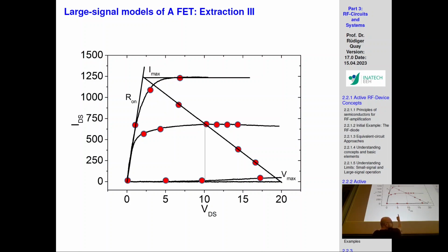how much is the swing of your input voltage, whether it's a complete period, or whether the one side is only positive and the other side is cut off, and what the effects are with respect to the output. Probably this was given in other lectures, so I don't have to introduce that now, but more operating points are selected, and from these operating points you try to deduce the non-ideal effects of driving a device into saturation, to model them into your circuit so that you have a model. And when you have that model, you can put it into ADS and start to design.